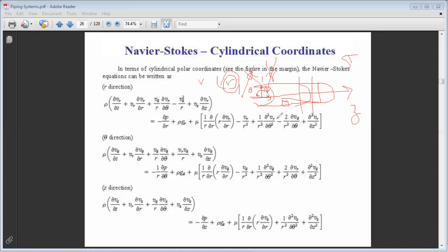Okay, and our velocity is only along z because the fluid moves parallel to the axis of the tube. So velocity is along z and is just a function of r. Now see how much simplification we get in our terms. We take the Navier-Stokes equation in polar coordinates, because when we have a cylinder, the best system to consider is cylindrical coordinates. We said it's a steady application, so every derivative with respect to time will cancel out.